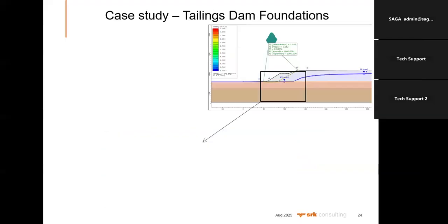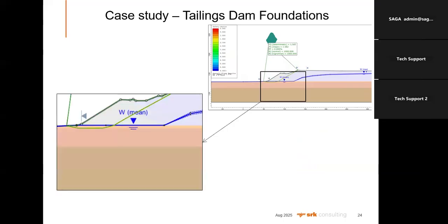And in the Bushveld complex tailings dams that a lot of us work on, we have this igneous rock setting as a foundation. And you often see these straight line things in stability assessments. These are cross sections for stability assessments. When I see straight lines like that, I just know it's absolute bogus. This is an igneous rock setting. We simply don't have that.